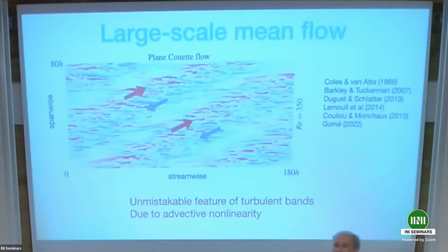And basically, all the flow can do is blunt the profile. As the mean profile comes into the turbulent region, it blunts. As it exits, it re-accelerates, blunts and re-accelerates, blunts and re-accelerates. That's all it can do. There's not a whole lot of freedom there in terms of what this mean profile can do. I understand it has a certain amount of structure as a function of radius, but basically its centerline increases or decreases. It can't turn directions or do anything very weird.